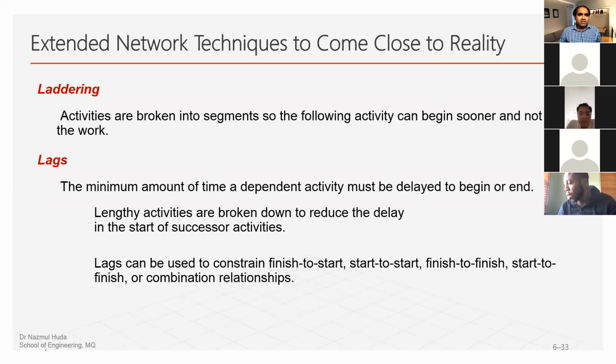Then our next topic is layering, an extended network technique. Now that we have the basic structure of the project network diagram, let's look into some more fundamental details of the project network diagram as we go into more complex areas. What is layering? An activity is broken into segments so that the following activity can begin sooner and not delay the work.